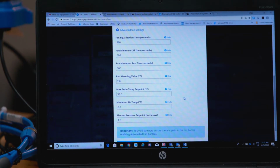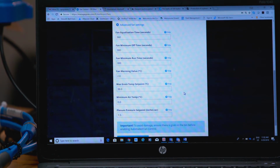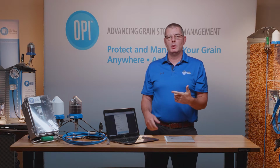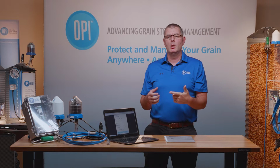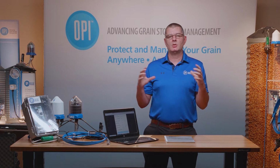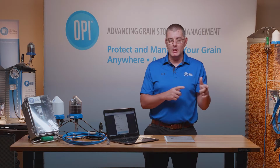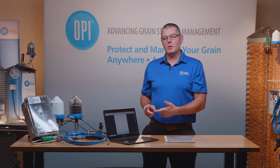The next thing on there is actually the fan warming value. And that's what we talked about earlier. When the fans do spool up, the friction it creates with the air and pushing the air in there creates a pressure change, and that actually warms the air going into the bin. So we want to make sure we measure that.